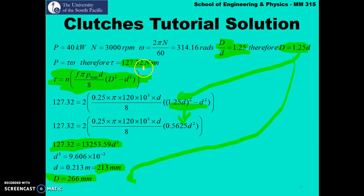So just once more, it's a uniform wear case. It is effective on both the sides. So therefore n is 2. Now what happens is your diameter ratio. Your diameter ratio is the outer diameter divided by inner diameter, which is given as 1.25. So substituting for that and then simplifying, you should end up with these values.